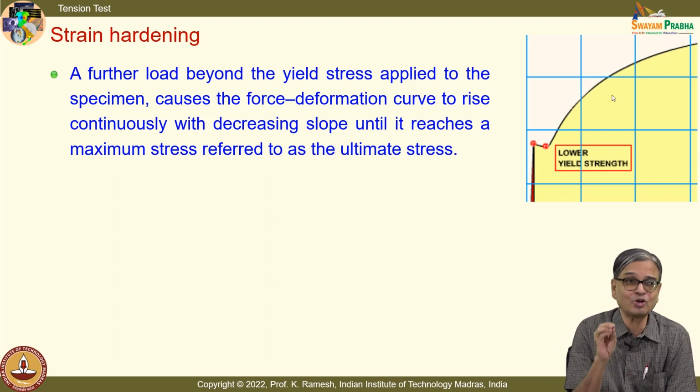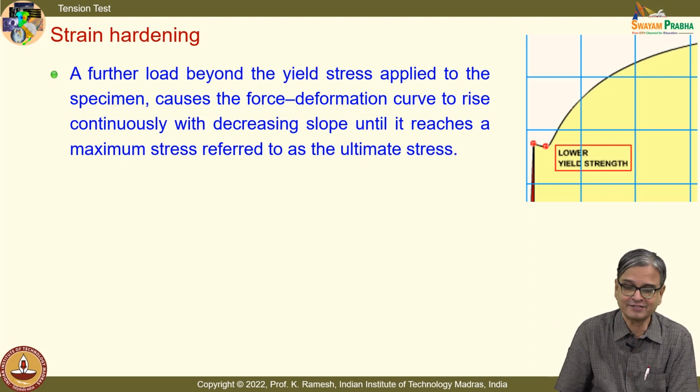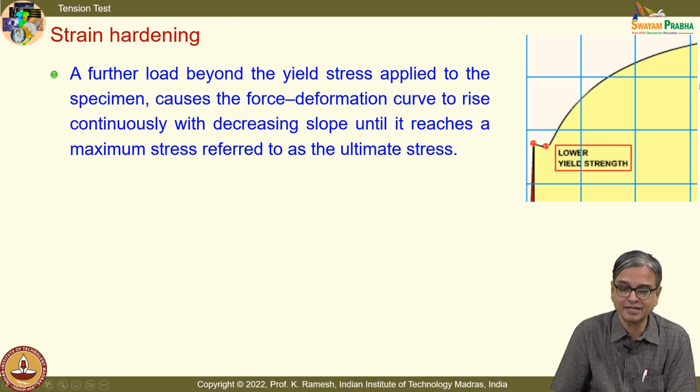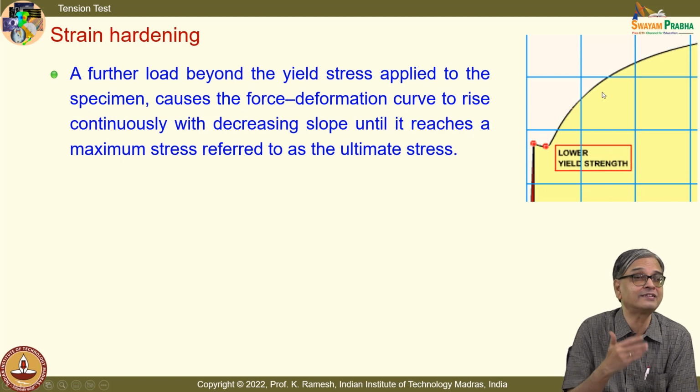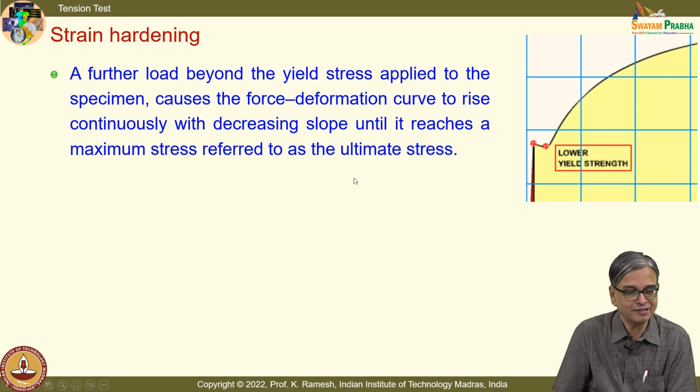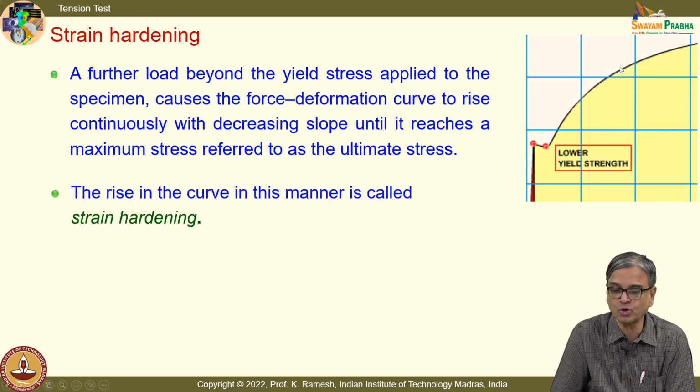It is just because we have modeled only the linear portion that strength of materials has developed. So we want to keep this out and say this bombastic name, strain hardening, as if strain is increasing the strength of the material. It is not to be interpreted like that, but the term implies this. You have the slope, it changes, and then it becomes horizontal when you go to the ultimate strength.